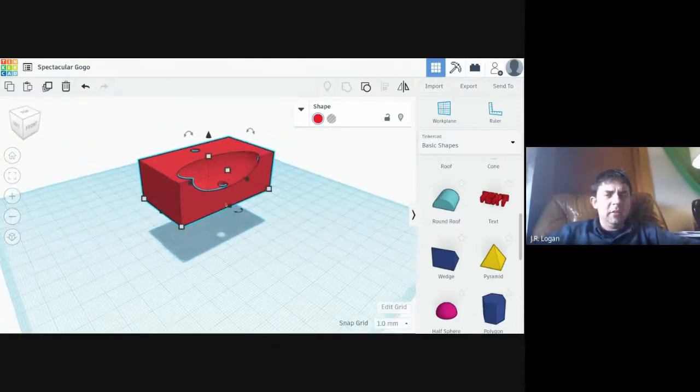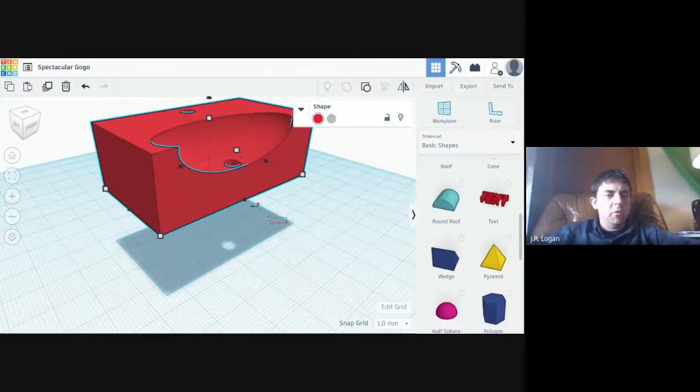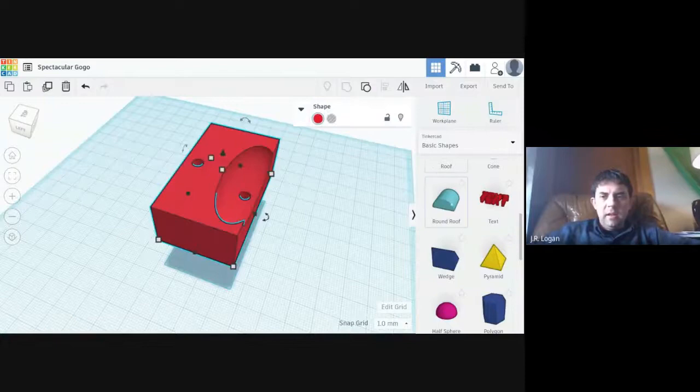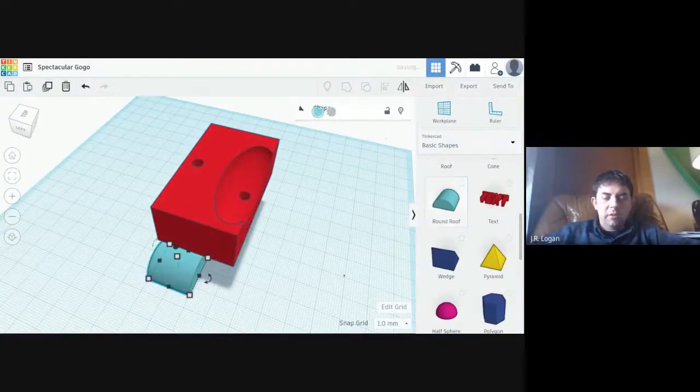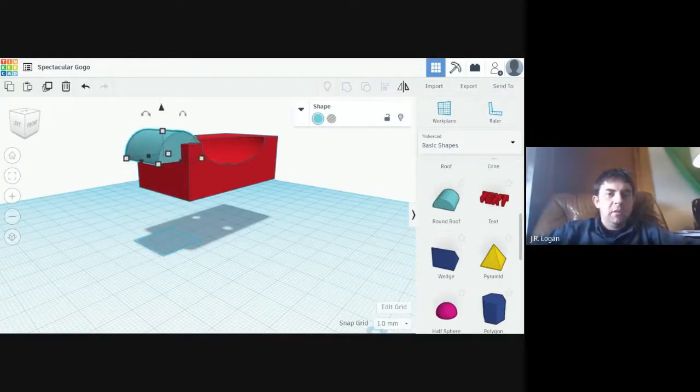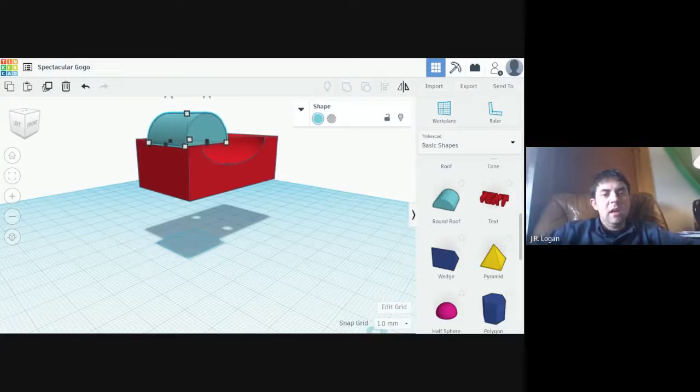When you're aligning things, there's a couple of tools that you should be aware of as well. So you can move objects bit by bit by using the control keys. So I'm just using the cursor keys, the arrow keys on my keyboard, and I'm moving those around. And then if I hit control, the up and down arrows move to moving up and down. So this I find sometimes is more accurate than moving around with the mouse.